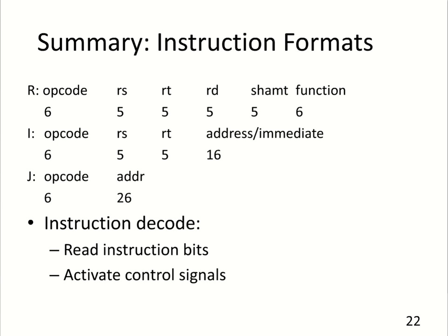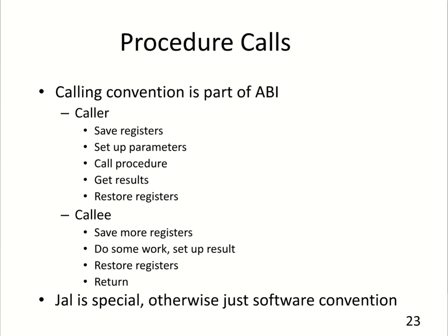for the jump. Now, what does the instruction decoder have to do? It has to read these bits, a 32-bit chunk, out of instruction memory, and it has to then specify the control signals that are needed to actually execute the semantics of this particular instruction using the data path components that are in the data path. In subsequent lectures, we'll see exactly how this works, and in your project, you'll actually be implementing the combinational and sequential logic to accomplish exactly this task.